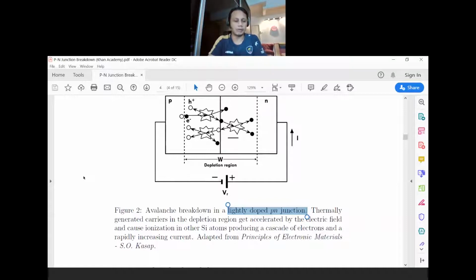We've learned last time, if you change the forward bias or reverse bias, you will actually change the depletion width, right? In the case of reverse bias, the depletion width gets a lot wider due to the high negative voltage applied across the junction. It will also impose a huge electric field across the junction.